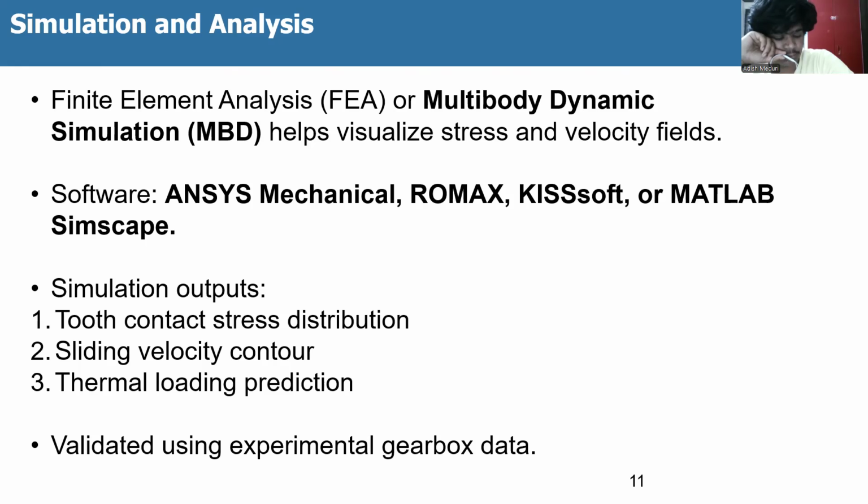The simulation outputs are tooth contact stress distribution, sliding velocity contour, and thermal loading prediction, validated using experimental gearbox data. So these are the finite element simulations and analysis.